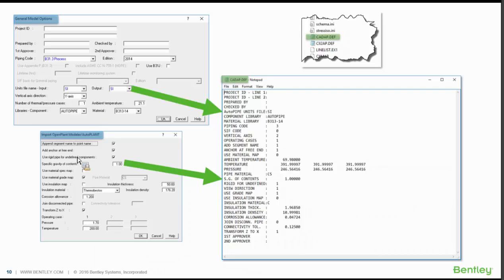For an imported system, they've got some disconnected flanges on elbows. How do you fix this so there is no disconnect? Okay, so again, while importing here, we have the ability to join the disconnected pipe. And you can see in this example, we left this unchecked. We didn't have any situations like that. Everything connected nicely. But if you go through the import process and you find that you're getting some disconnects, or you're seeing some anchors randomly being placed throughout your model, that's because you have those disconnects there.